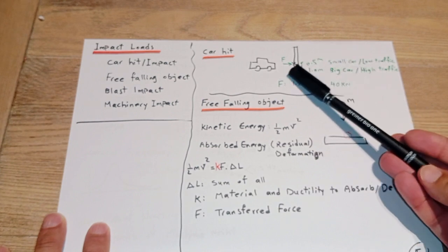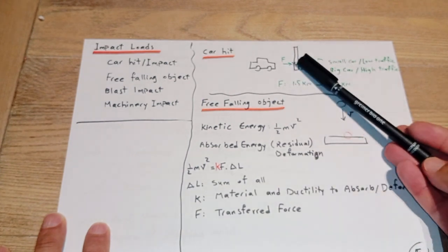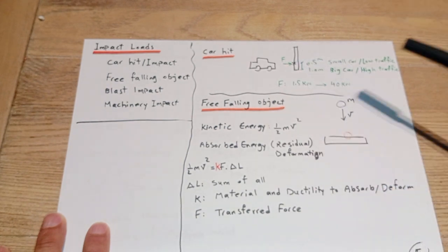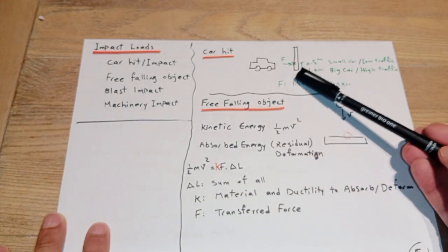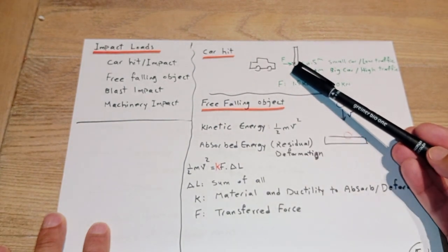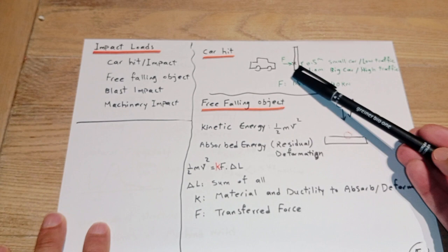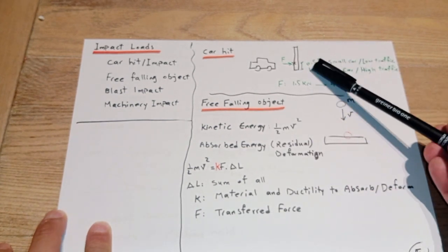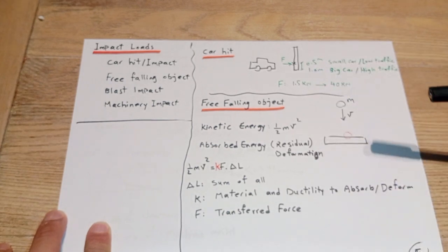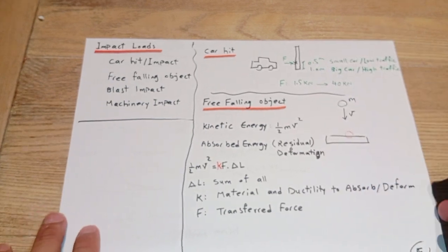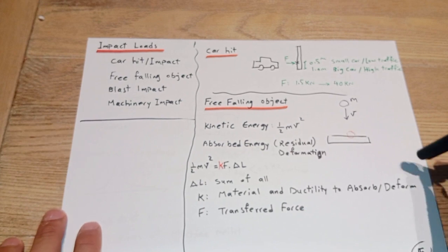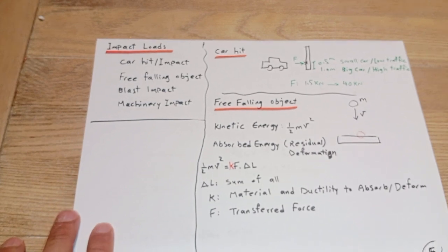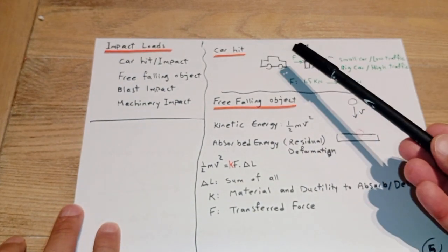And then we're going to have just a structure with load and impact points. So we will have shear effect and bending effect, and we're going to design the structure. And just remember, from the other videos, in this case, the restraint on the ground is a very critical parameter, and we need to care about that one. And sometimes we need to have some pile or just a very strong foundation for this one to take the soil, to avoid rupture of the soil due to very big loads.